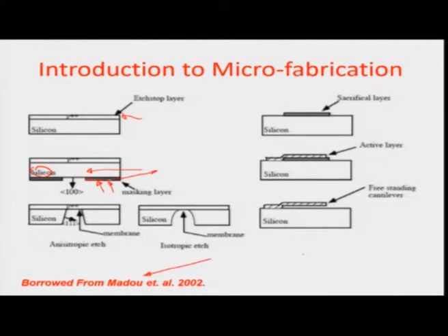So, let us say in this region the chemical will not be able to get in touch with the silicon which is inside, and wherever there is an exposure, like in this region where there is no masking material, it will start the etching process because the etchant has contacted the particular surface through which there can be chemical removal or subtractive machining of the particular area. So, you can carry out etching in many ways.